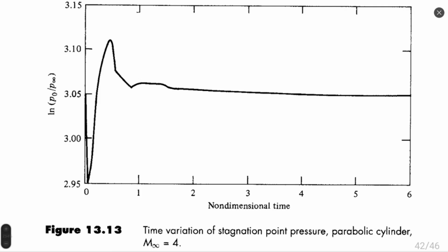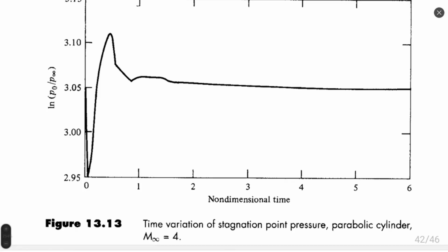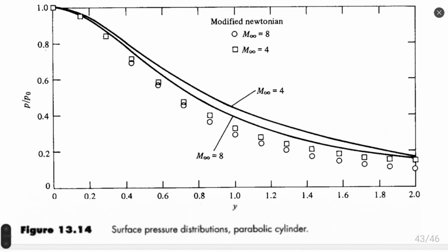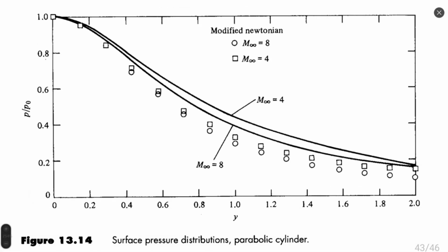And with the time, at first time steps, it changes, right? At time steps more than 2 already, this change of relative stagnation pressure is smaller and smaller. So from step 4 to 5 and from 5 to 6, especially, extremely small variation. So we can assume that flow is converged. Depending on the goal of your simulation, you can choose different convergence criteria, not just flow equations, but also others.